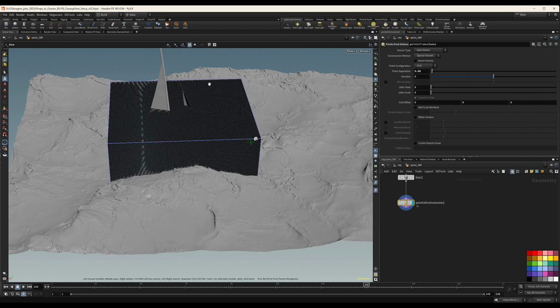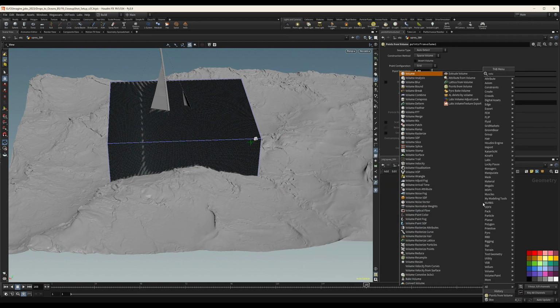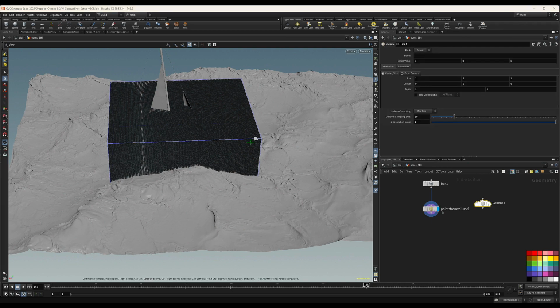We're going to mesh this just to create a bound, because it's easier to kill the points based on the camera than the mesh, because with the mesh you need a lot of resolution. So what I'm going to do now is create a volume from the camera. Remember that we did this before. I'm going to call this density. It's a scalar, and I'm going to set this to 1, 1, and 1.